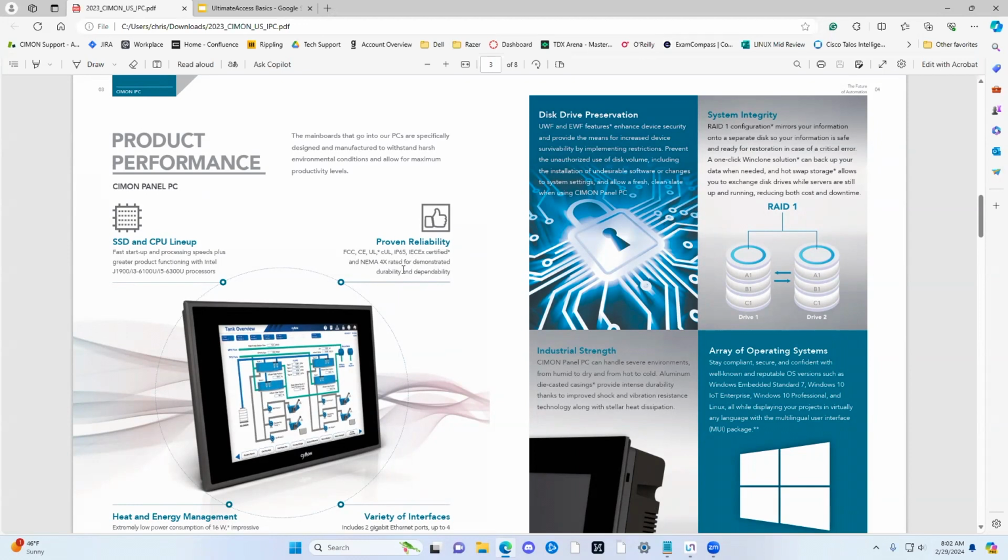How does it compare to an HMI? Well, as opposed to an HMI, it provides more capabilities in terms of processing power, memory, and more communication interfaces. It can be much larger. Some companies offer 21-inch, 19-inch HMIs, but it just depends on which company you're dealing with, right? And IPCs can run Linux, they can run Windows, they can run your third party proprietary software or your own software. It just depends on the use case. So it has a lot more computing power.